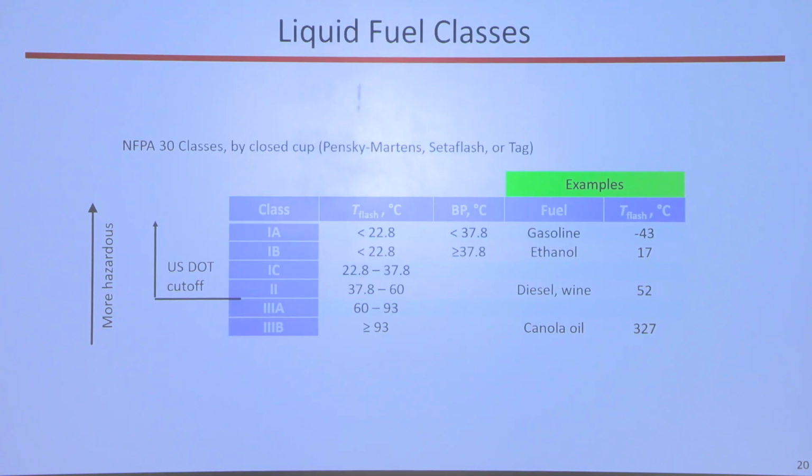precautions. So what's shown here is the flash point temperatures, down around 22 for some things like gasoline, super flammable, and ethanol a little bit less. Diesel, if you want diesel to burn, there's a broad range because diesel isn't a monomer. There's no molecule called diesel, but somewhere between 40 and 60 degrees is the temperature you need for diesel.